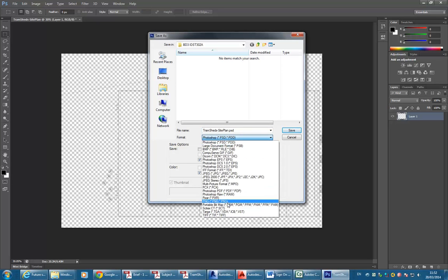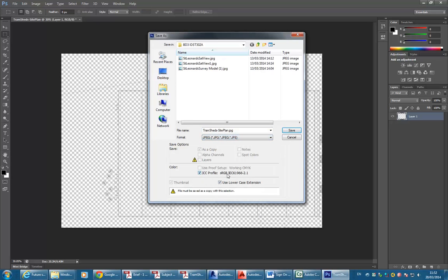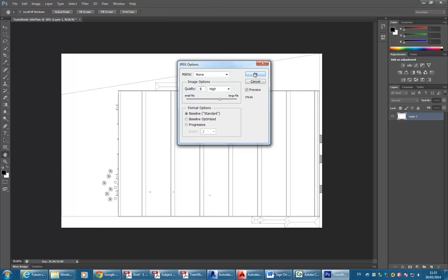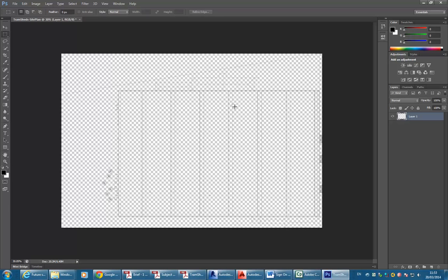And also, if you want to go into Revit, it needs to be a JPEG. You can't insert PDFs directly into Revit. So this is just a useful thing you need to know. If you need to insert a PDF file or something that you only have as a PDF into Revit, simply open it up in Photoshop and then do what I'm doing now: save as JPEG. Then you'll see it'll lose the transparent background. Not here, but if you saw it just a moment ago, it did flash with a white background because JPEGs can't store transparencies.